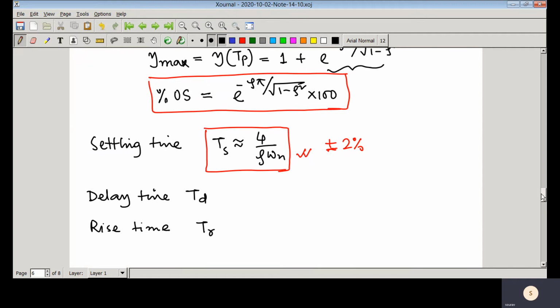So we can take one second order system and vary zeta, as there is no explicit relationship between the damping ratio and TD and TR. We can plot the delay time and rise time from the response, and from there, by fitting a curve, we can get a relationship.